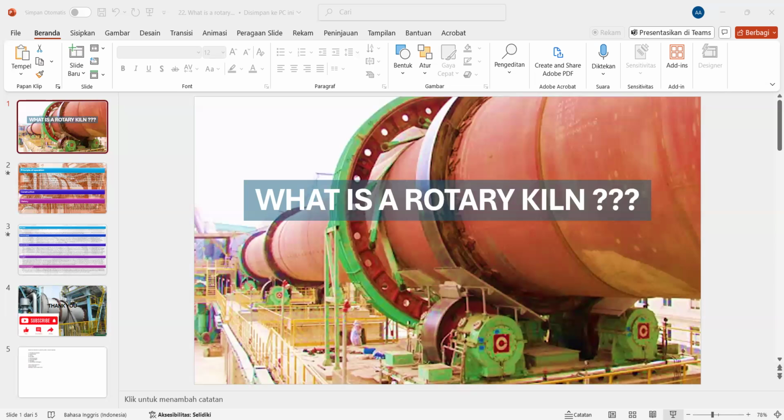The hot gases may be generated in an external furnace or might be generated by a flame inside the kiln, such as a flame projected from the burner pipe or firing pipe, which acts like a large Bunsen burner. The fuel for this may be gas, oil, or petroleum coke, or fairly finely pulverized solid fuel. The basic components of a rotary kiln are the shell, the refractory lining, support tyres, riding rings, and rollers, drive gear, and internal heat exchangers.